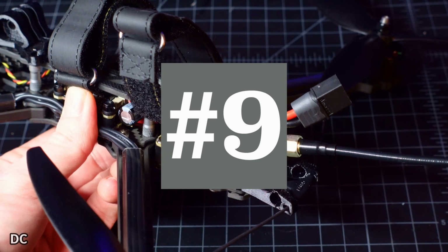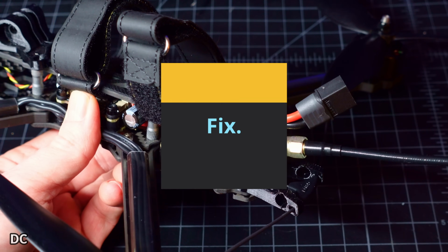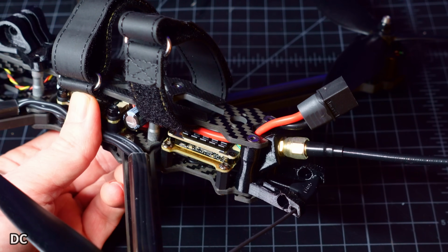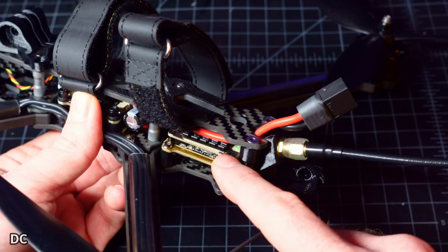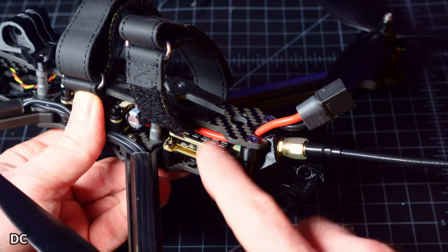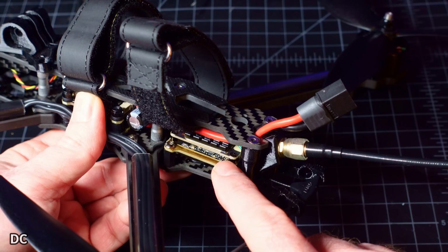Now, a tip for the analog guys: if you have a drone that has tons of static, and when you fly 20 feet or 30 feet away, you're having a lot of static in your goggles, and you've done everything you think you possibly can to try to figure out what is going on with your video signal, you made sure you're not on 25 milliwatt, you're cranking full power. I know people have these 2.5 watt VTXs now, and talked to someone recently that said, oh, I'm having such trouble, I'm getting so many lines of interference.